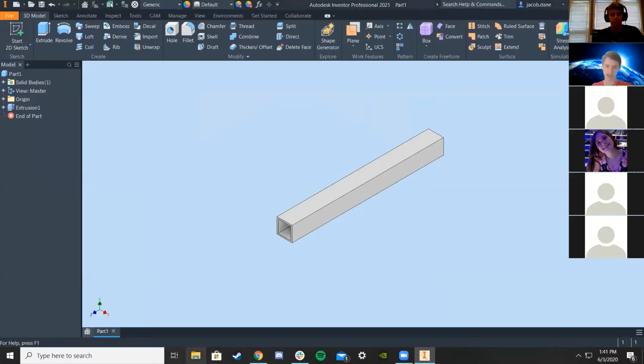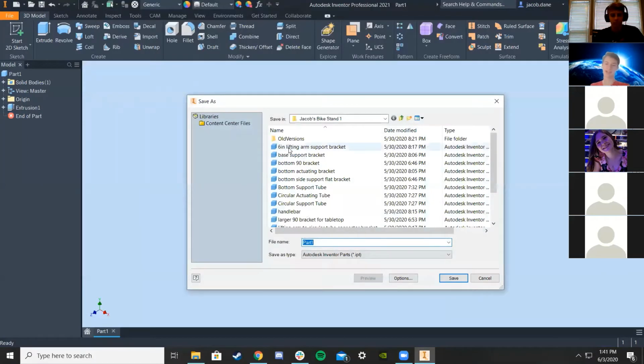So I'm just gonna do that, but actually I have to save this first. Obviously you want to save often in CAD, especially once you get to super big assemblies, because it's going to start taking a lot of processing power. And if you accidentally do something that gets close to breaking the sketch, you can make CAD crash. Then if you haven't saved, you're going to lose all the progress you just had. So make sure to save often, especially anytime you start doing anything big inside your assembly.